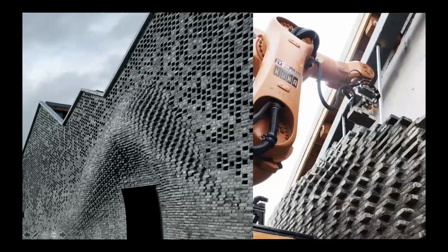You can see we have some quality in this curvature, and all the bricks were recycled because it is an industrial area. We collected the bricks from a teardown project and selected the ones not broken. We try to set up a relationship between the roughness and the accurate location of the brick. We put 3 different sensors on the top of the robot effector, and we can figure out the geometry center of the brick. So we control the geometry center, but actually the shape of the brick is not very accurate because they are recycled bricks. But you can see this very interesting quality produced by the machine, a collaboration between the machine and the human.